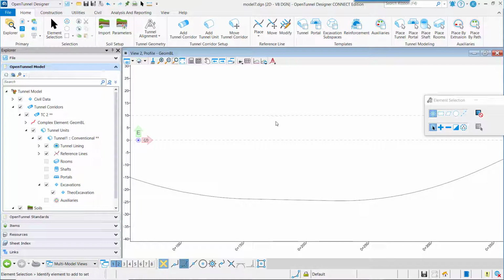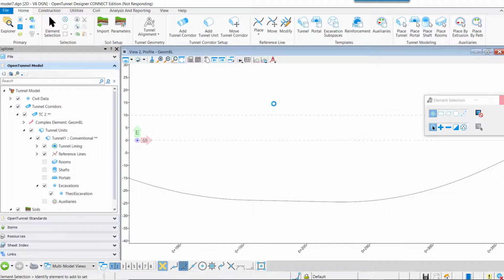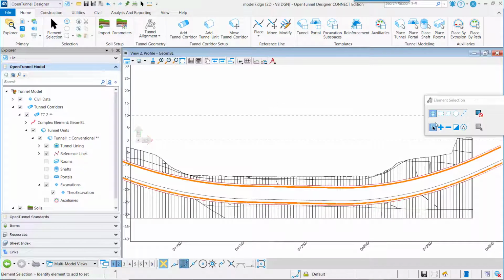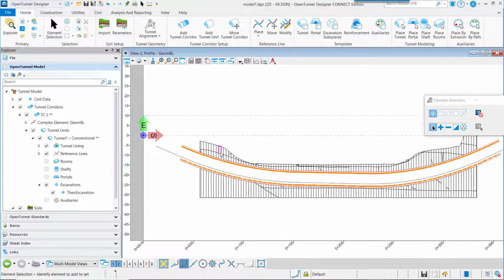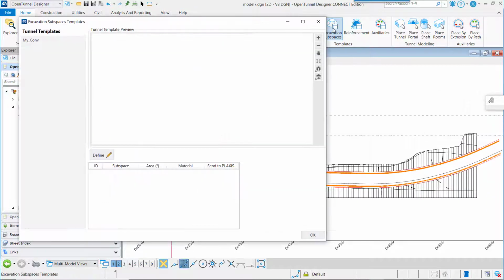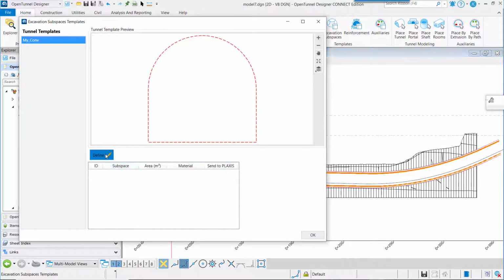This will take time, as it will remove all the display of the crossed elements and recompute crossing the different elements. And we can check here exactly, so you find everything. You see the ground has been removed, and we can see the lining, which is filled, and the hole that we have between the lining and the excavation.